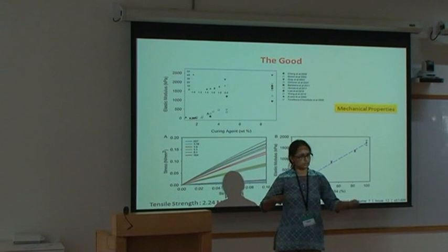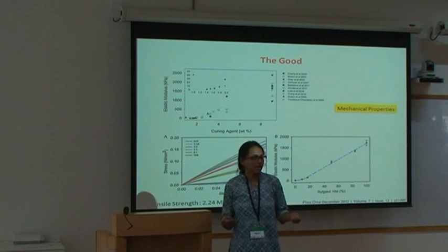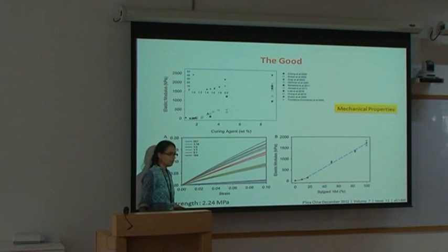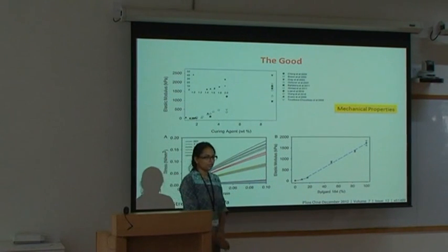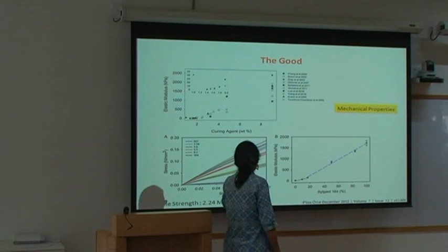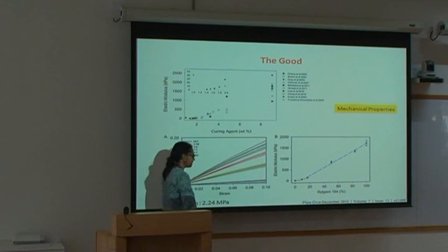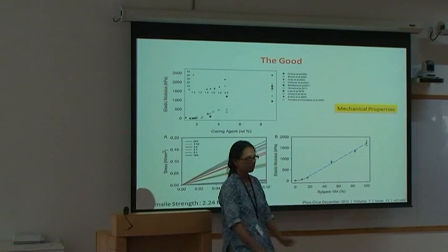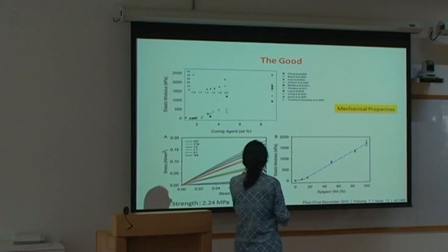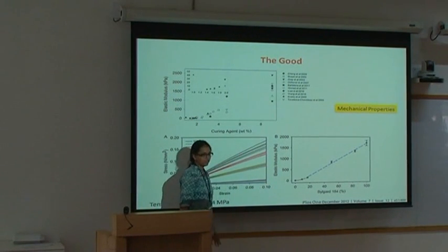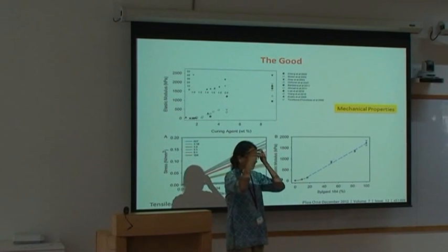It becomes more difficult to strain it. It becomes more rigid, and of course, remember that after a point it will break. But a good thing is that that's a big enough number. It's not really as good as even a rubber band. A rubber band can take around, I think, 15 megapascals, or human skin is around 30. But it's good enough for our experiments that we saw yesterday, doing almost 100% stretch, and it doesn't break. So this is linear only in this regime, between 0 to 20% stretch, after which it starts becoming non-linear.